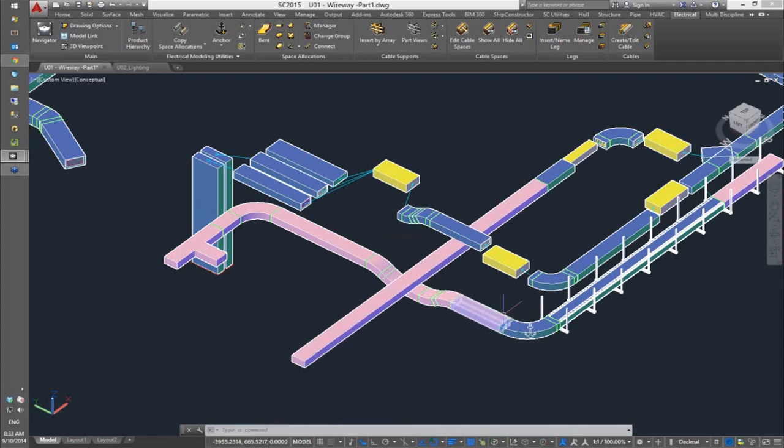They're modeled in a standard drawing as a separate part. So when I was inserting one of the things we looked at there, and I'm sorry, I'm a bit tight on time to go back and actually pull up the dialogue, but when I filtered down to my part type, I had 3 different downcomer lengths. So I picked the particular one which was 18 inches for this one. I had a couple of others defined for this particular part type, but those do have to be predefined.